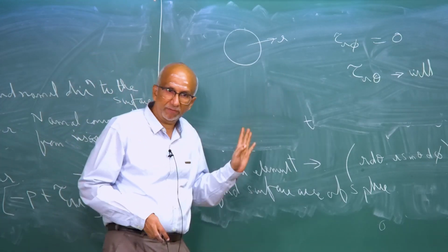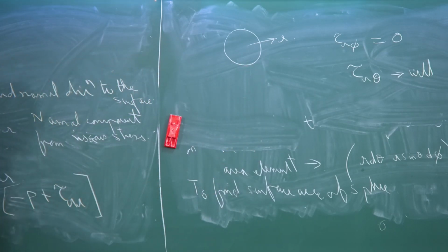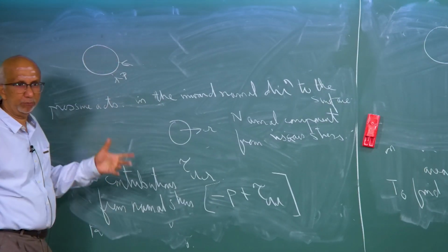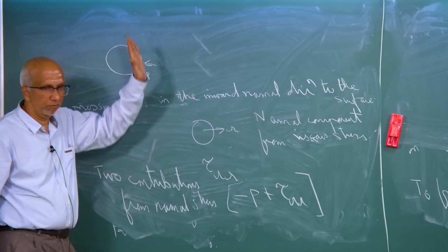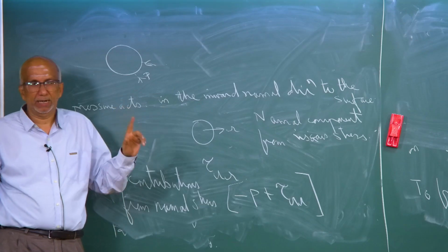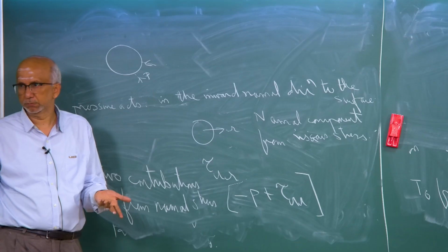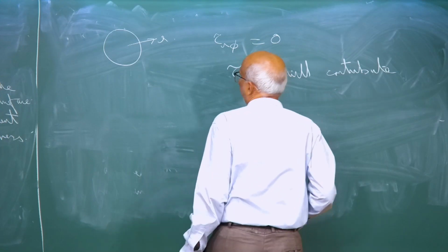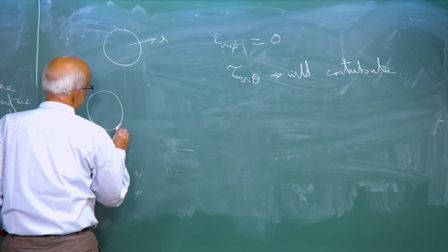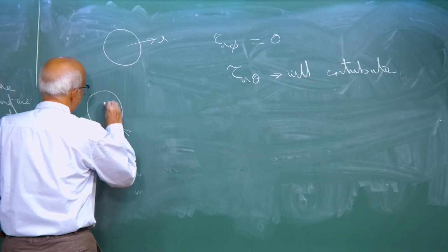So, this will also have a component along the direction of the flow. This is acting normal to the surface at every point. So, what I have to do is resolve it in the vertical direction, and then integrate it over the area. Then I get my force. That is the concept. If I take an area element here, just to explain to you, this is the normal direction, and this is the theta angle.